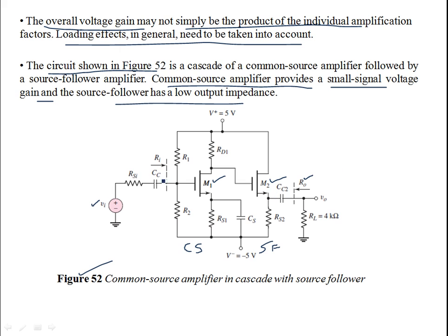So CS over here is a bypass capacitor, CC is a coupling capacitor that couples the AC signal over here. Then again, this is a coupling capacitor which will pass the AC to the load. But for the purpose of DC analysis, which we have considered so far, you don't need to consider the capacitors. All the capacitors are open for DC analysis. Okay, so they are all open.